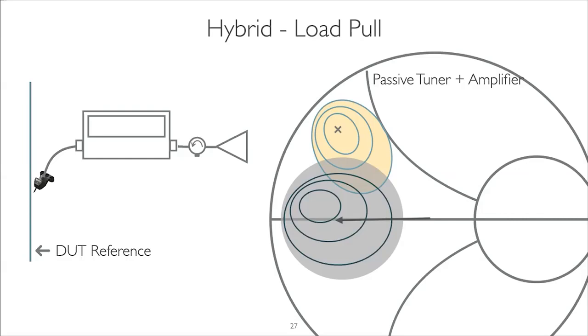This is a scenario where you're capable of having a smaller loop feedback amplifier combining with a broadband tuner, which, for example, might be able to do fundamental but harmonic as well. So a lot of people really focus on optimizing the fundamental impedance, combining the passive and the amplifier, and then doing some harmonic tuning using, let's say, a 3-frequency tuner that allows you to do very flexible measurements at the fundamental while holding the harmonics at specific impedances.